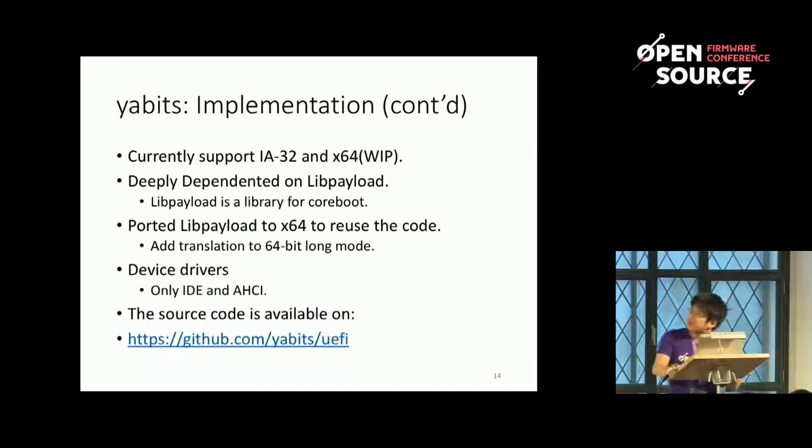And Yabit is deeply dependent on libpayload, which is a library for coreboot payload. And I also ported libpayload to x64 to use the code base. And so I added some translation from protected mode to long mode.